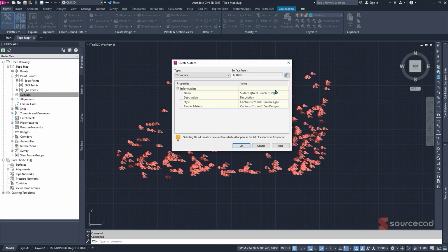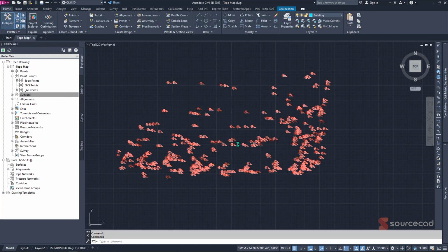As you're fully aware, Civil 3D usually creates layers for us to use. And then you can even change the name just by double clicking here and give it a specific name that you want. Let's say EG, which means existing ground. So let's use caps, EXISTING GROUND. Then you can change even the style of representation of this specific area. So once that's done, you click on OK.